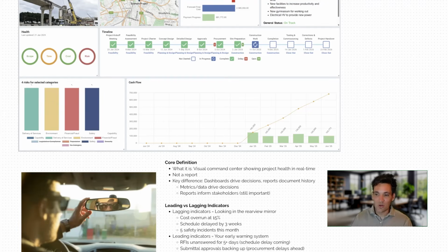You could look at your productivity rate for a certain activity. You could be 25% of the way through and achieving only 75% of the planned productivity. Again, you can clearly see that we're going to overspend on that package, and we're identifying this at the 25% point of the work.